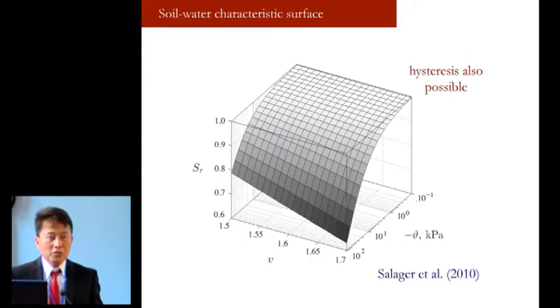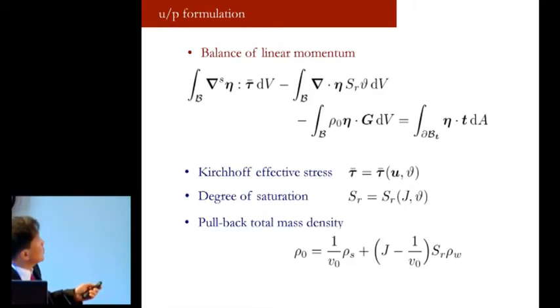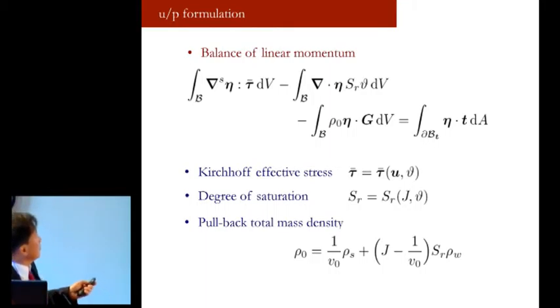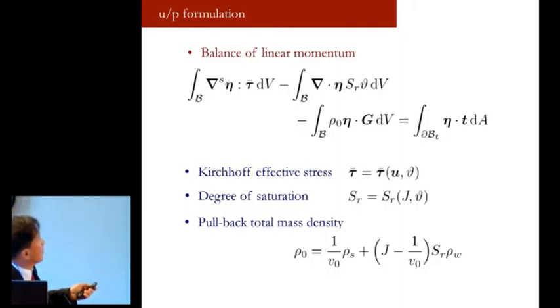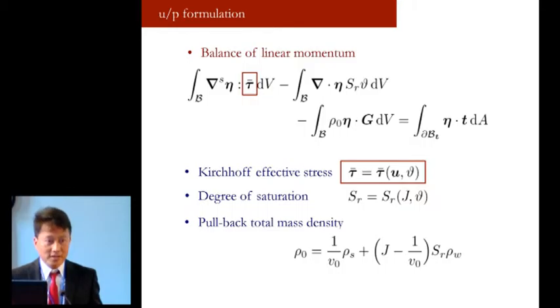Next, I'm going to show that everything can be encapsulated in UP form, where U is the displacement of the solid and P is the pore water pressure. First of all, we consider the balance of linear momentum for the mixture. So the first term here involves the effective Kirchhoff stress, tau bar, which, as we know, can be expressed in terms of the displacement of the solid matrix and the suction stress.